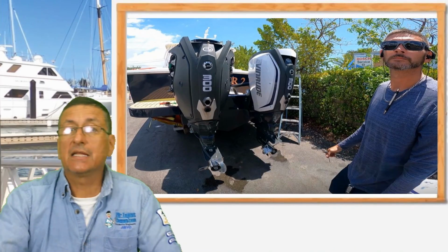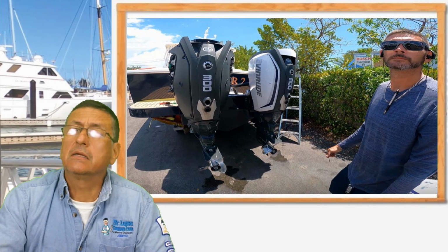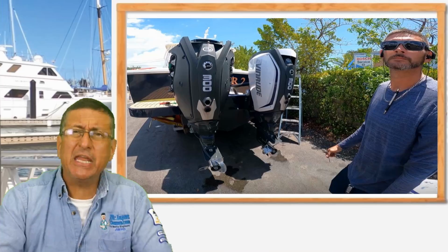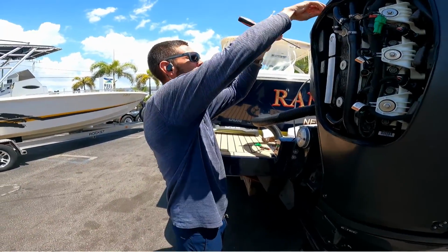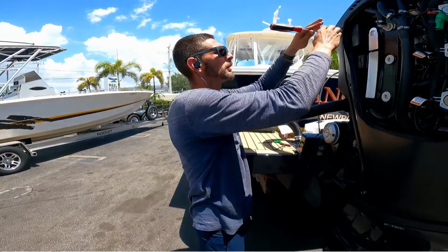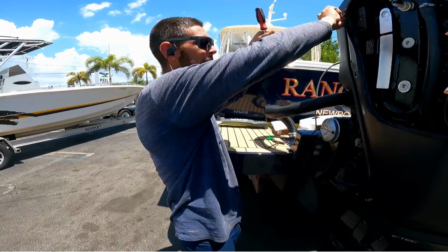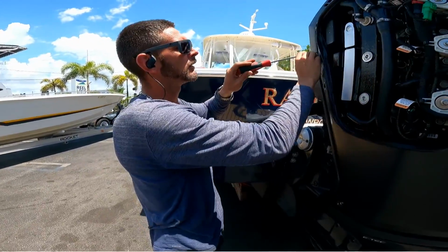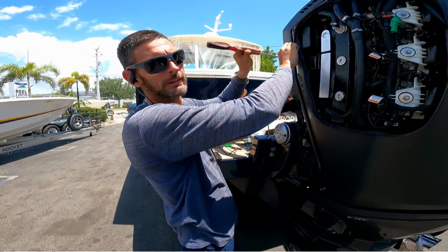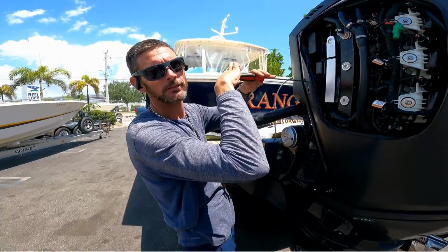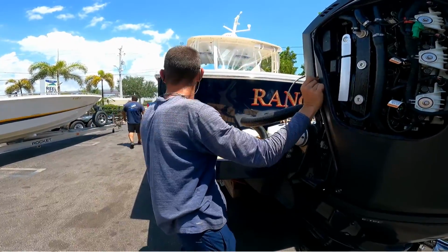Okay, after that, Danny connected the computer and the scanner, and he identified some errors, some codes. How many codes, Danny? In different modules. You connected the scanner and you found 7 reports. I downloaded all 7 reports. You've got an engine report for each engine, a control box report, and what they call a surface mode controller, which controls the joystick. There are 2 of those, then a pressure sensor module, plus the joystick assembly. Okay, perfect.